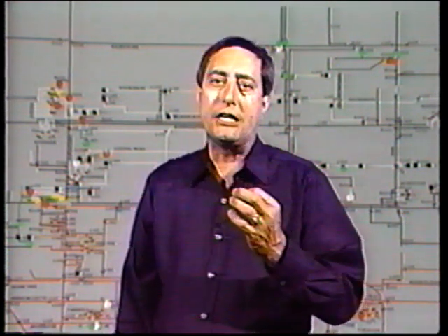As we mentioned earlier, on large, high-voltage buses, a bus fault should be cleared as rapidly as possible due to the extremely high value of current which can flow into the fault. On the other hand, the last thing we want is for the bus to clear all of the breakers for a fault out on one of the connected circuits. What we need is high-speed differential protection which is reliable.